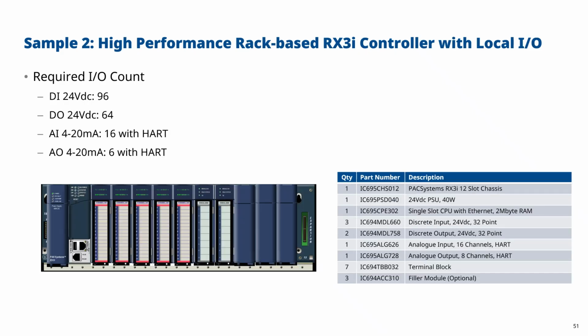Now here I've got a slightly larger system, so not much larger than before. It probably doesn't deserve using the CPE 200, except there's a requirement to use HART I/O. So for HART, then the only good HART solution we have, including HART pass-through, is using RSTi I/O.